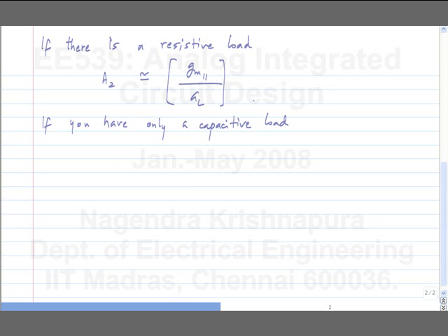What is more important, the GM of the output stage or the GDS? GM also affects the second pole, right? This is in both cases, by the way. This is in the extreme approximation where CC is much greater than CP. So, the bottom line is the final stage GM is what is important, not so much the GM by GDS ratio. So, you use close to minimum length.